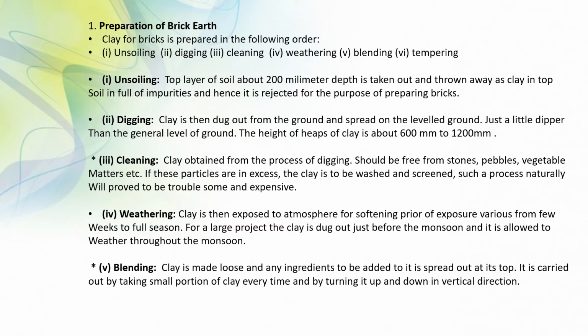After that, preparation of brick earth. Clay for bricks is prepared in the following order: unsoiling, digging, cleaning, weathering, blending, and then tempering. What is unsoiling? Top layer of soil about 200 mm depth is taken out and thrown away, as clay in top soil is full of impurities and hence it is rejected for the purpose of preparing brick.